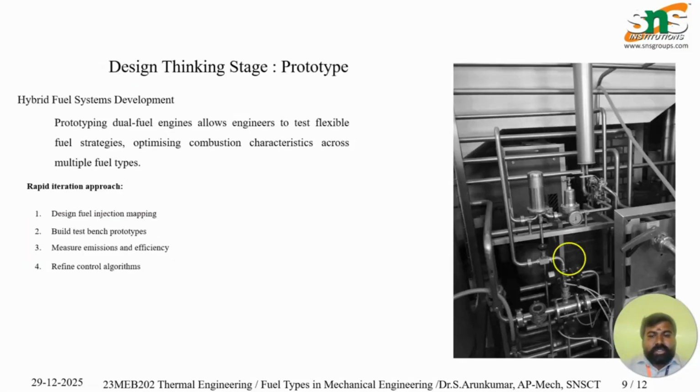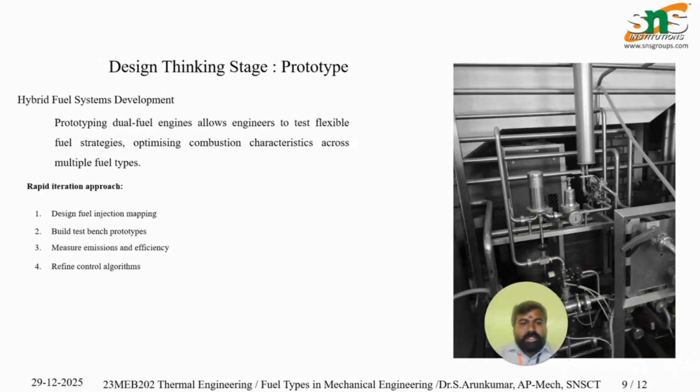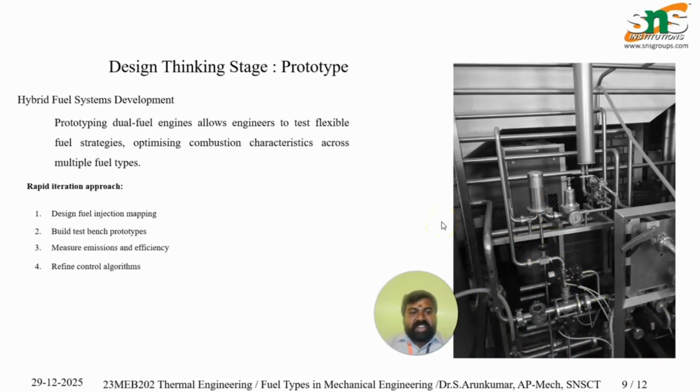In hybrid fuel system development, prototyping dual fuel engines allows engineers to test flexible fuel strategies and optimize combustion characteristics across multiple fuel types. Some of the rapid iteration approaches are to design fuel injection mapping, build test bench prototypes, measure the emissions rate and efficiency of the engine system, and refine the control algorithms. These are some rapid iteration approaches for these fuel types.